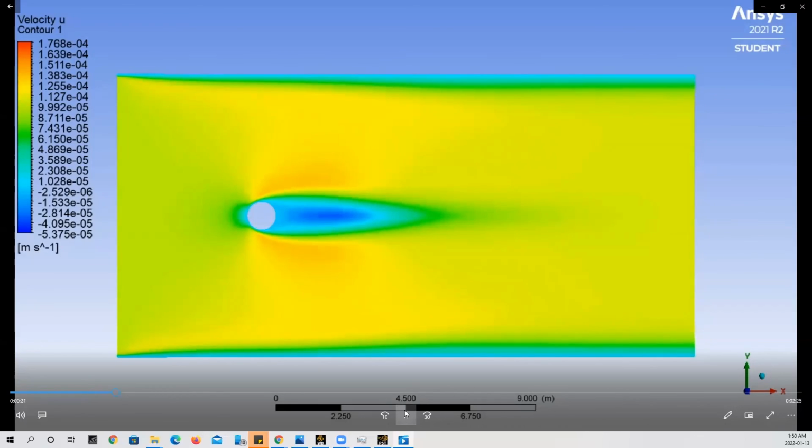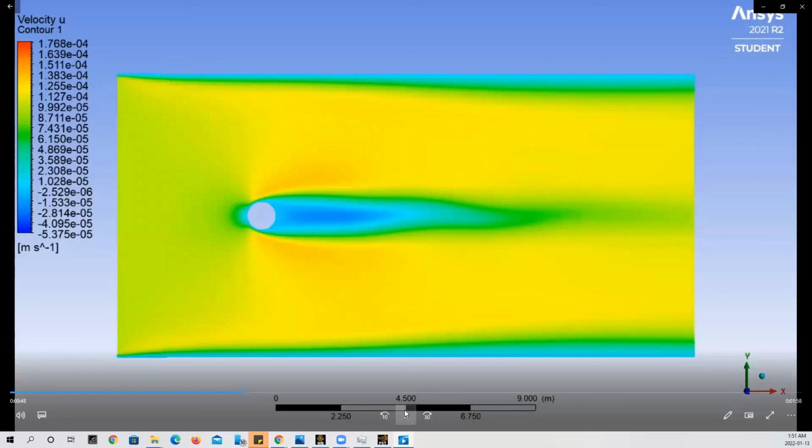The other thing that we could obviously do is reduce the range of our animation. But this is a pretty cool animation to watch because we can see it right from the beginning, where the von Karman effect is not taking place. There's not much happening. And we are naturally seeing slowly the progression of the vortices starting to shed from our cylinder. So I hope this tutorial was helpful for you guys in order to do the fluid flow around a